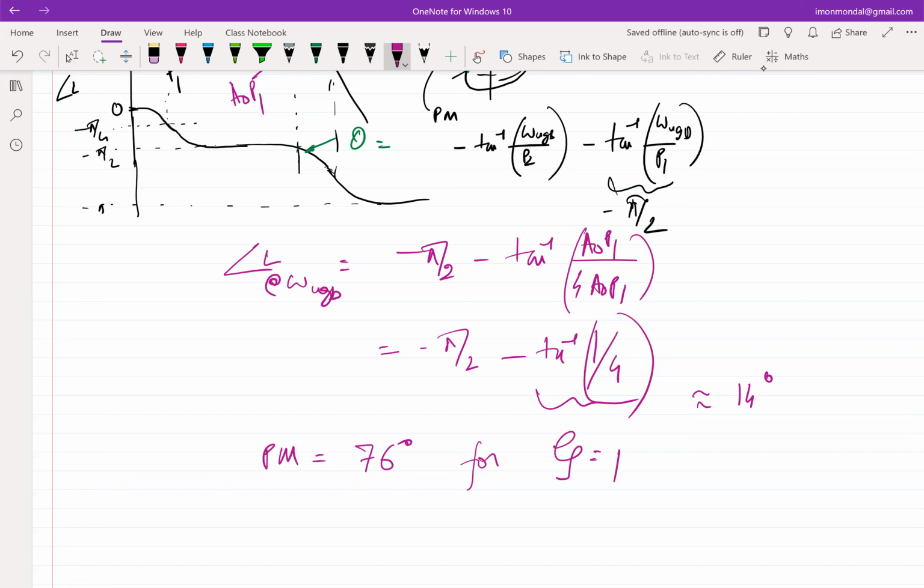We do it through the domain of phase margin. We find out the phase margin for any order system, and we say that if it's 76 degrees, it will behave similar to a second order system of phase margin 76 degrees. That strictly is not true, but that's something we get by with. It works. So that's why phase margin is one of the popular margins.